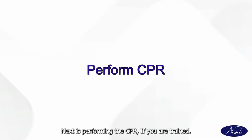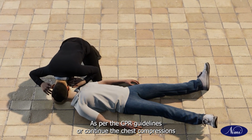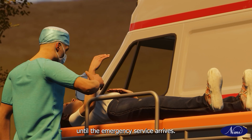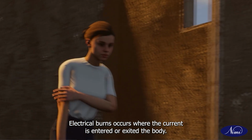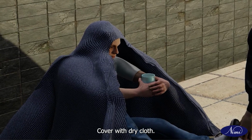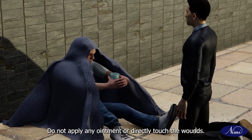Next is performing the CPR. If you are trained, do the chest compressions and rescue breaths as per the CPR guidelines, or continue the chest compressions until the emergency service arrives. Next is treatment of burns and injuries. Electrical burns occur where the current entered or exited the body. If the burns are visible, cover with a dry cloth. Do not apply any ointment or directly touch the wounds.